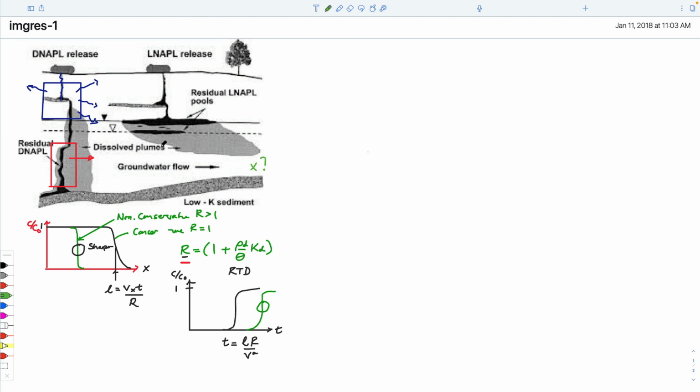for lighter than water fluids, the form of the saturations that we'd expect to see in here, the rates at which we think fluid would go through these, controlled by relative permeabilities and the residual saturation, the prospects for being able to suck this out if we try to. If it's close to full saturation, perhaps we can. If it's not, then all we'll suck out of here is water.